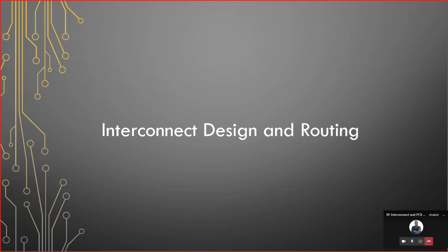Now, I'm not going to cover the vias in this section. The reason is that oftentimes you will see a recommendation that you should never use vias on RF signals. I'm going to show you an application later where you actually have to use vias. You really don't have a choice. You absolutely have to use vias in order to make this application work. For now, we'll focus on the transmission line design portion, and then we can get a little bit deeper into the application areas later.